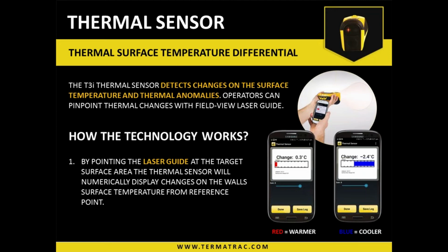One of those is that people seem to think it is X-ray vision, and it's not. Thermal technology only measures 1/1000th of an inch of the surface material. So it is no penetration at all on solids or liquids with thermal technology. It is not X-ray vision. It cannot see through walls. It is only picking up surface temperature differentials.